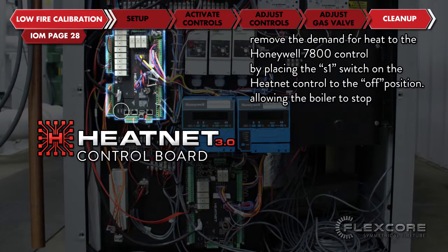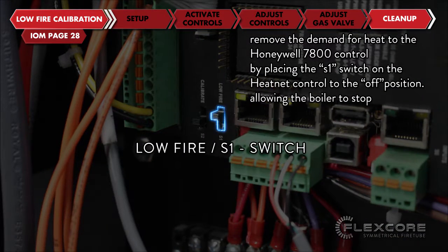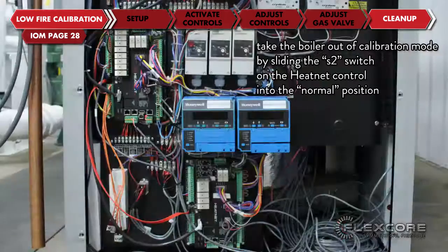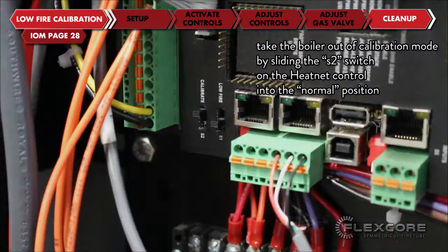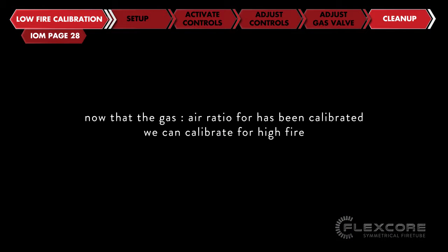Remove the demand for heat to the Honeywell 7800 control by placing the S1 switch on the heat net control to the off position, allowing the boiler to stop. Take the boiler out of calibration mode by sliding the S2 switch on the heat net control into the normal position. Now that the gas-air ratio has been calibrated, we can now calibrate for high fire.